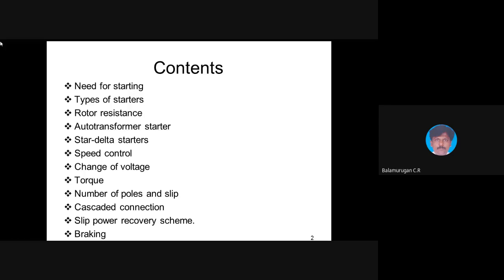And for that, we'll use a relay. We'll call that a thermal overload relay. That relay will be connected in all three phases and it will sense. Suppose the relay is connected in all three phases. Here the relay will not get any supply because there is no supply available in the B phase, and here we'll have excess current. Then the thermal overload relay will open the R and the Y phase, and you can safeguard the machine.